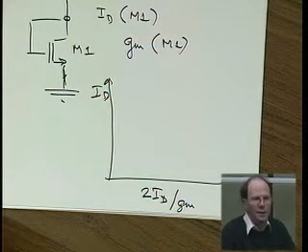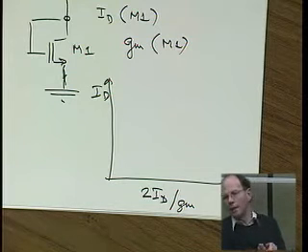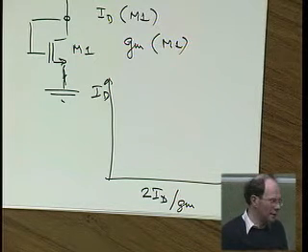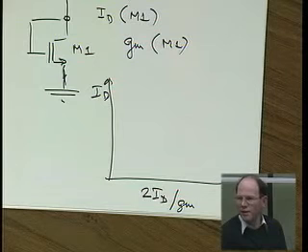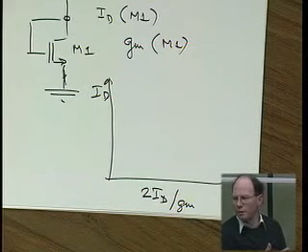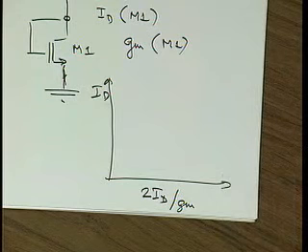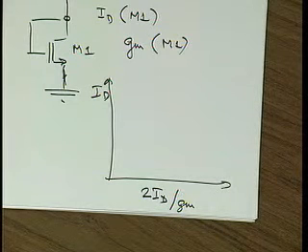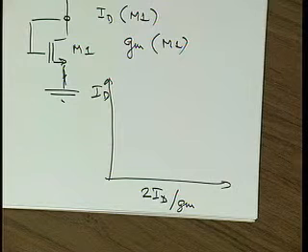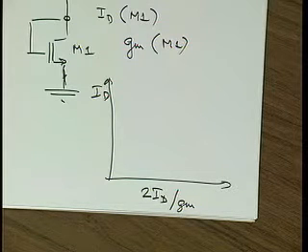Well, you can almost be guaranteed that when you stick in all the parasitics, when you lower the supply voltage to the minimum that you can deal with, you use the slow or fast parameters, you crank up the temperature to the maximum, 100 degrees C or something like that, the IC is still supposed to operate under. Most likely your beautiful design isn't going to work anymore.